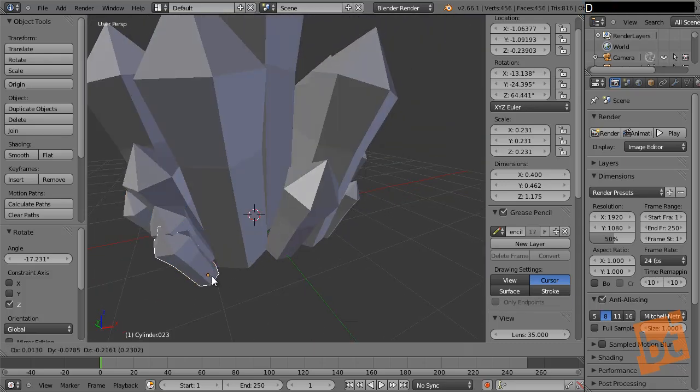And finally, another little trick is that while you're moving with G, you can just press the middle mouse button and you will see that line defining the direction in which I'm dragging the mouse. Okay, so the closer axis for that line will define the axis in which the object will move. So you can see if I drag it here, it will be moved in the Y axis. If I drag it like this, in the Z axis, and like this in the X axis.